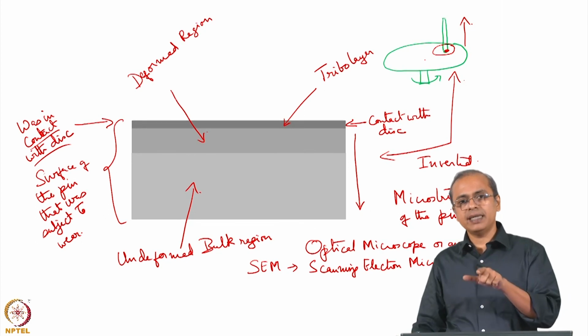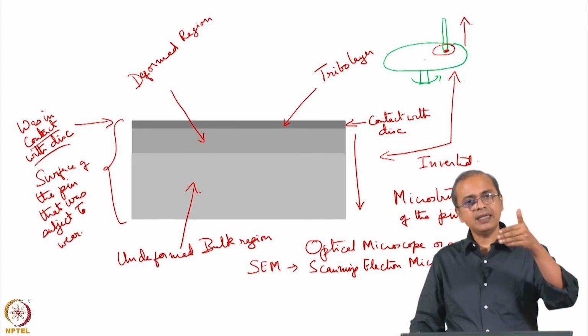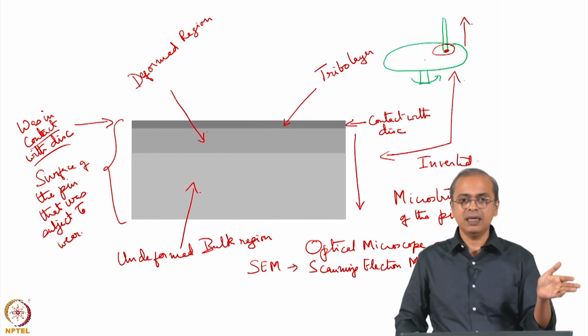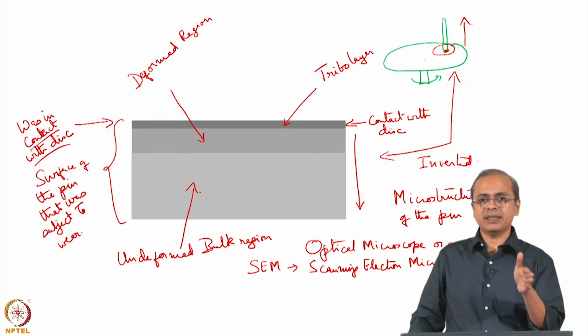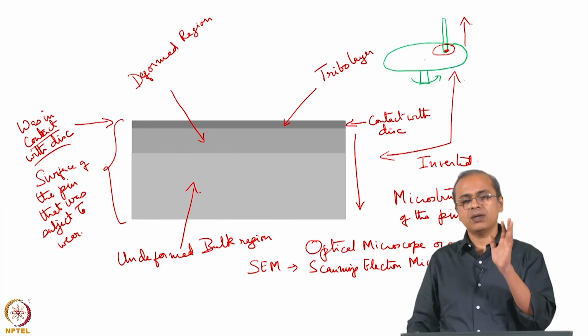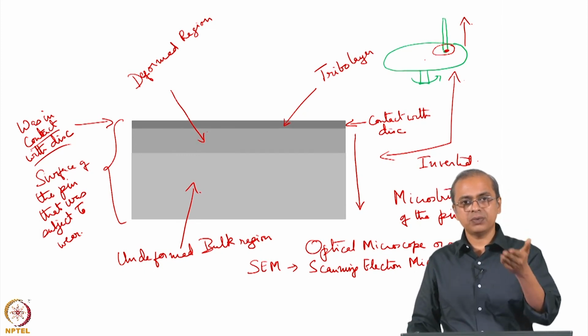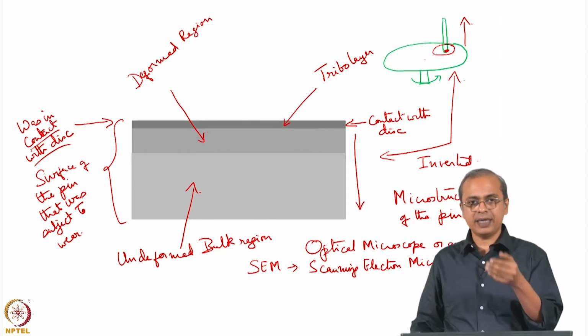Typically, if you take stainless steel and keep scratching it, then steadily the interior of that surface will keep getting oxidized, and then eventually the whole sample fails. So, any continuous abrasive action on a stainless steel structure will eventually break down that structure, and this is because of the surface oxide being a protective layer.